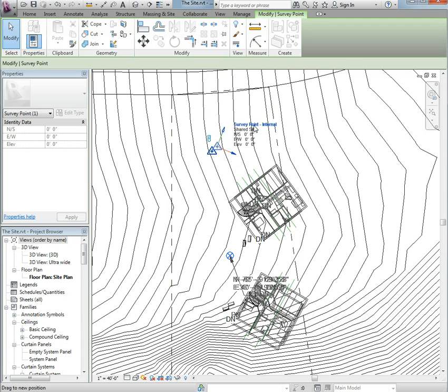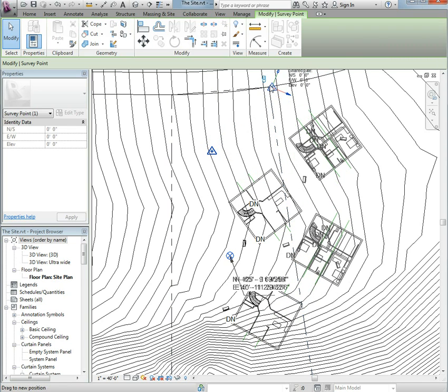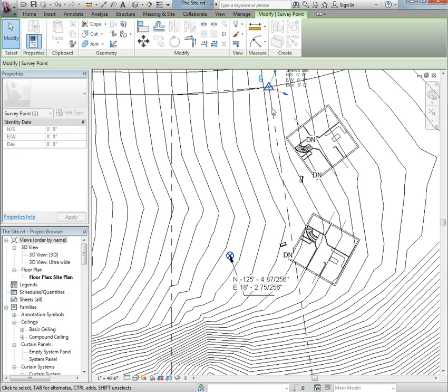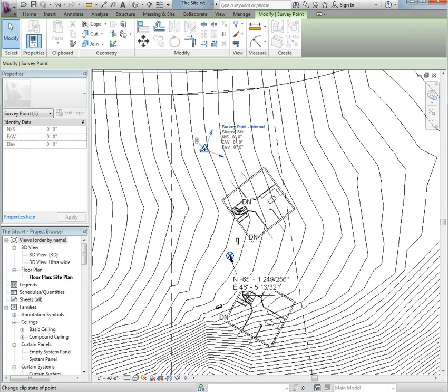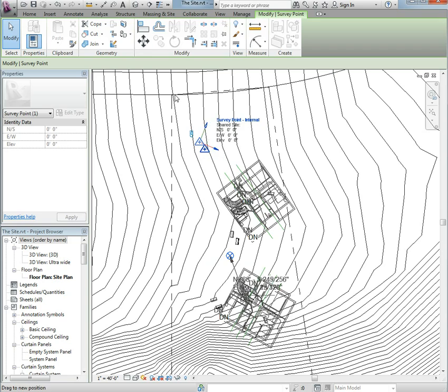And we're basically saying that the survey pin isn't there anymore. So I'm saying, okay, I'm going to move the marker over to this other pin, and notice that in the case of the kid knocking over the pin, this would be the wrong thing to do because now the houses have moved. This would only be the right thing to do if these houses were already correctly oriented to the survey marker in the linked file, and we just wanted to update where the survey pin actually was on this file, because maybe it wasn't in this corner.